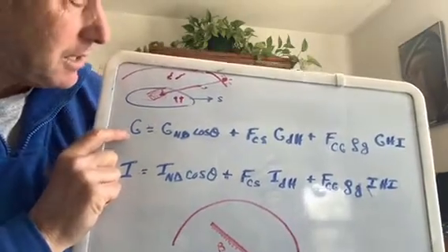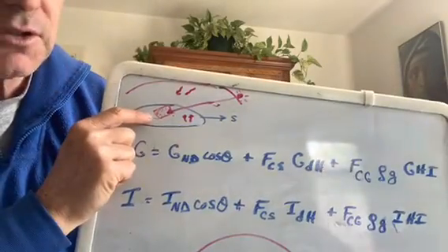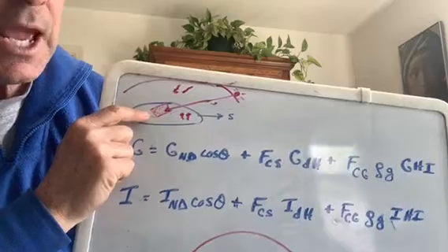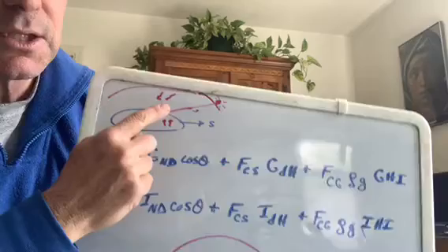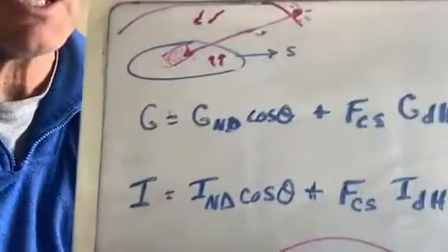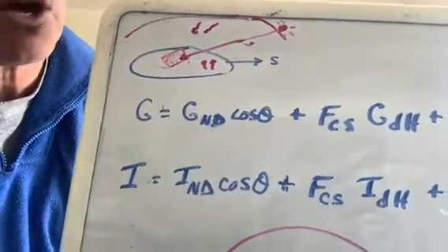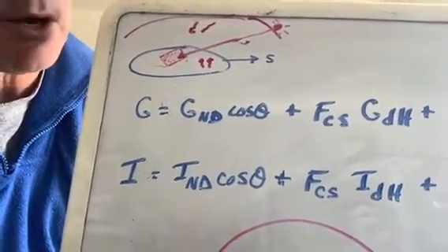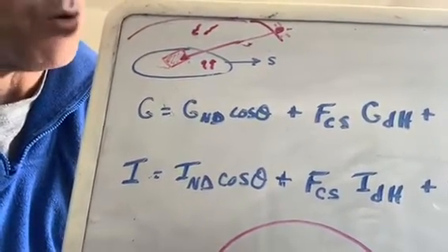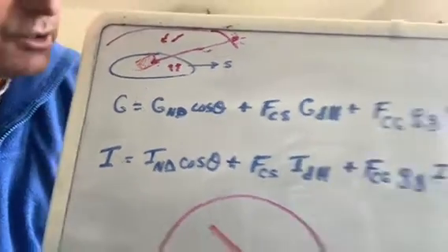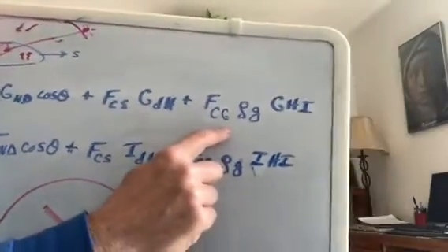So thinking conceptually how we get that? Well, here is a very, very crude picture. There's south. There's a collector that's actually not oriented towards south. And we're going to get 3 types of radiation on it. We're going to get the direct that comes from the sun. We're going to get the diffuse that comes from the sky. Okay, and finally, we are going to get stuff that comes off the ground, and some of that stuff coming off the ground is going to hit the collector. We have to figure out each of those, the direct, the diffuse, and the ground reflected, or there might be other reflections in order to get the total. So that's what we got here. We've got the direct, we've got the diffuse, and we have the ground reflected for that last term.